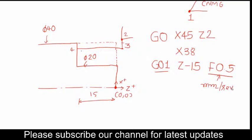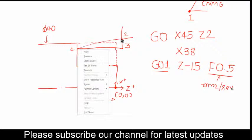Now we have to get back to point number 2, from point number 4 to point number 2. Since we have removed the material, we should not go back to point number 2 at a lower feed rate.